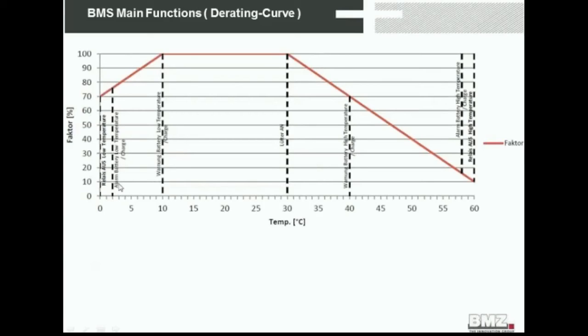In the world of SMA, an alarm message always means no more charging and discharging, or turning off the inverter can also be. At 10 degrees Celsius, we give a warning, low temperature, onto the CAN bus.